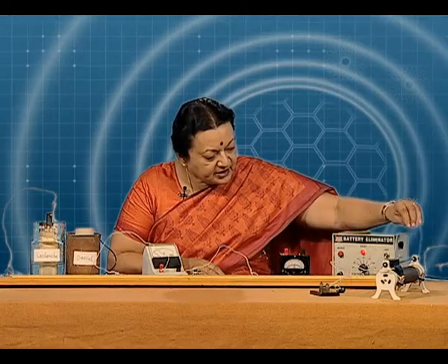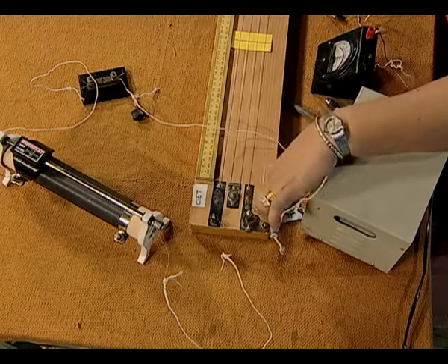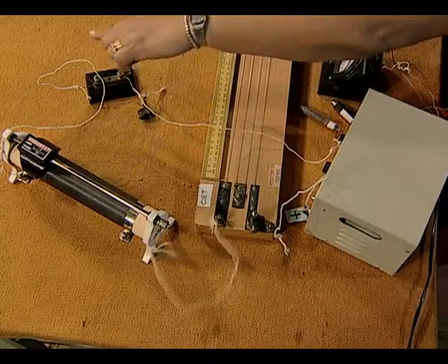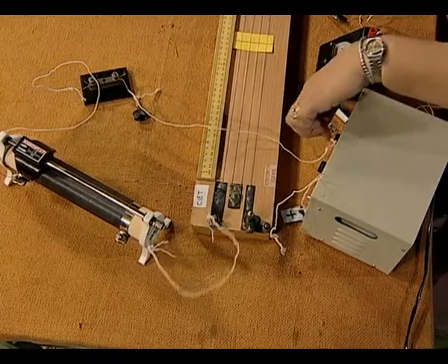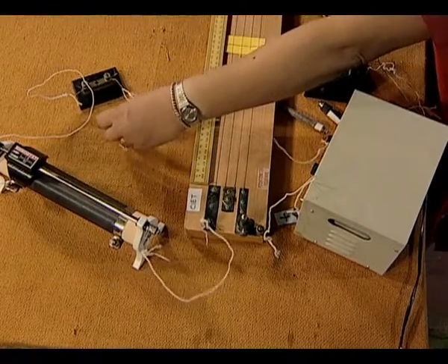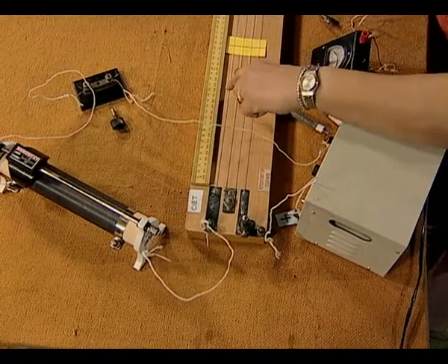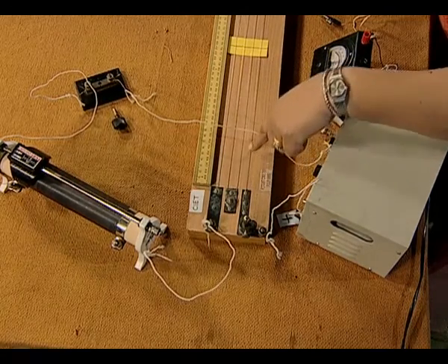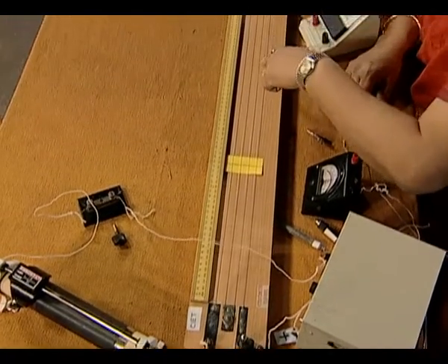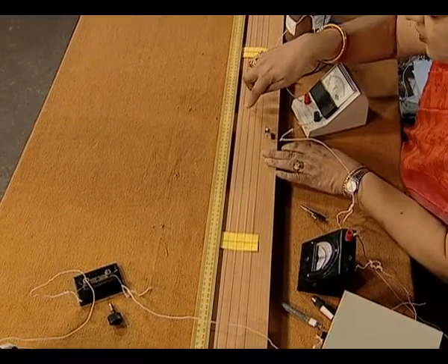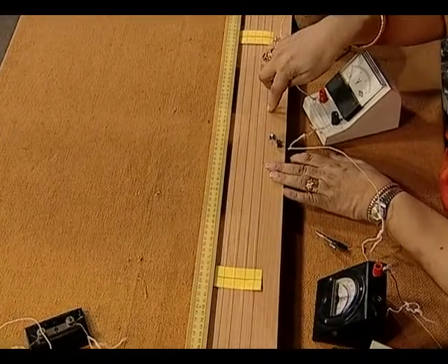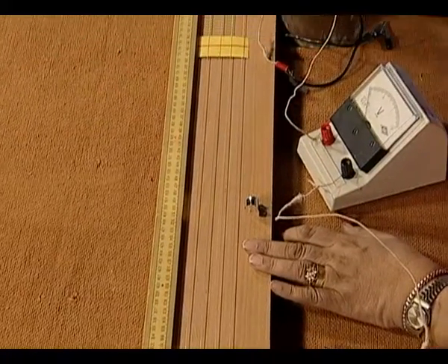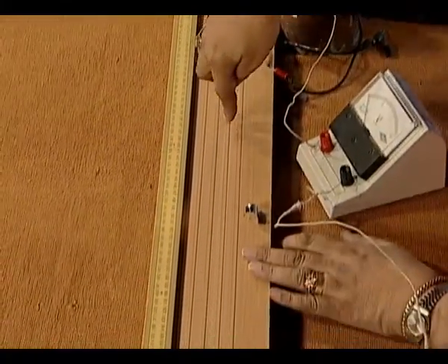Check out the circuit. This is the positive connected to this terminal, and all the way from here the negative goes via this rheostat and the key back to the eliminator. When I switch this on, there is a certain potential difference across this wire. The positive being here, the current in the wire would flow like this. This is a 4 wire potentiometer. So, we are dealing with 400 centimeters of wire. The current goes this way and comes in the wire along here.